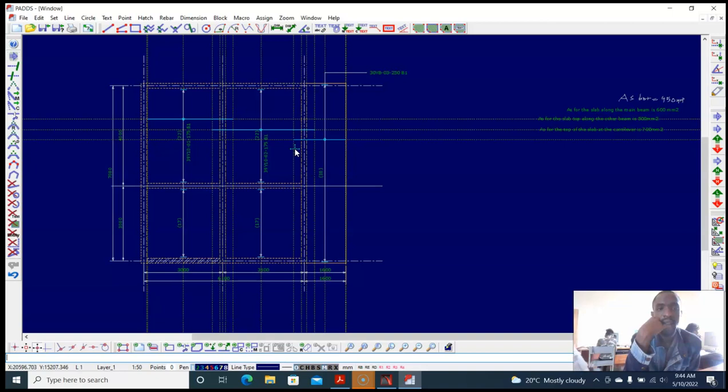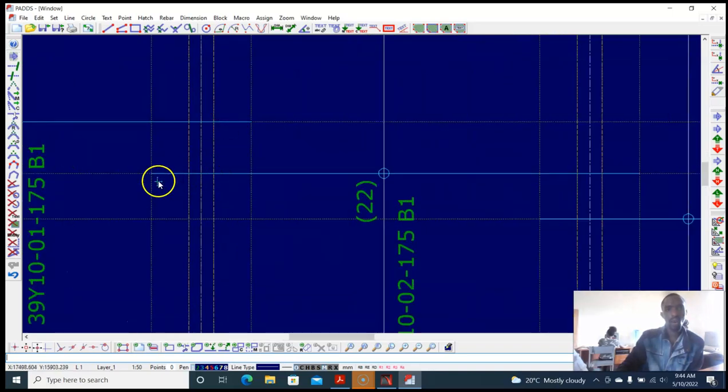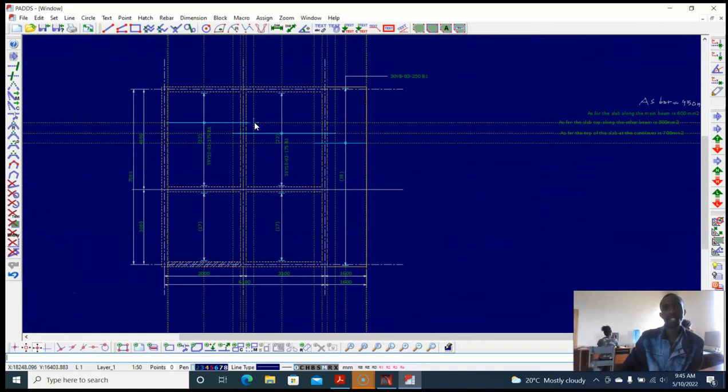The 50, we're using the 50, because here the slab is continuous and I want this rebar to cross to the other side. We're going to use 50 there. You can't choose 50 now, because if I use 50, the overlap between this and this is going to be so small. So the 50 is used at the edge. Yes, at the edge. Supposed to end at 300.